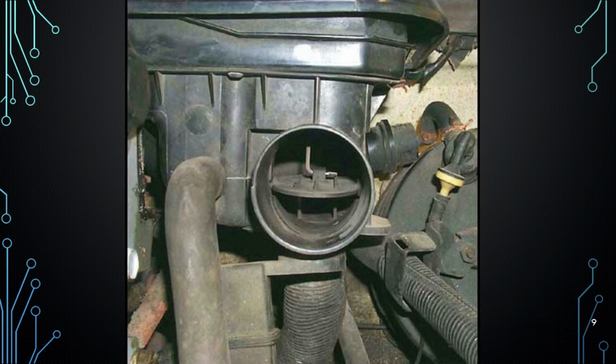That opening in the airbox with a flapper door is part of a warm air intake system. The flapper door controls whether the engine draws air from a hot source, like around the exhaust manifold, or from cold outside air. When the engine is cold, it pulls warm air to aid fuel vaporization. As the engine warms up, the door switches to draw cooler outside air. This improves drivability and reduces carburetor icing in older systems.